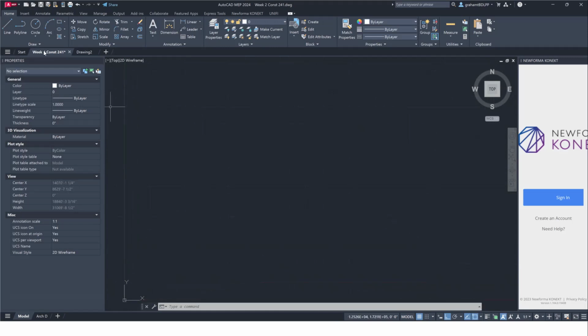One thing that you'll notice is in this template, if you want something to be 12 feet, you need to tell it you want it to be 12 feet with the actual foot mark, or 144 and enter. So this is in feet and inches. Any measurement you give it is automatically going to assume it's in inches unless you tell it feet.